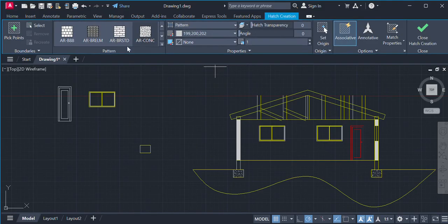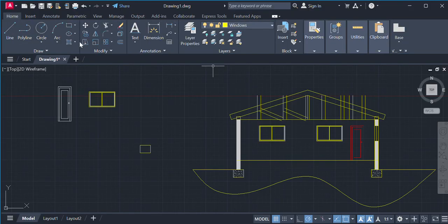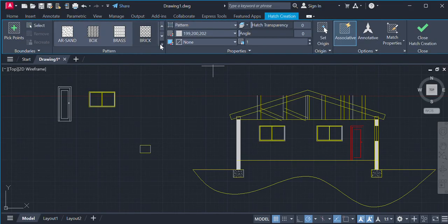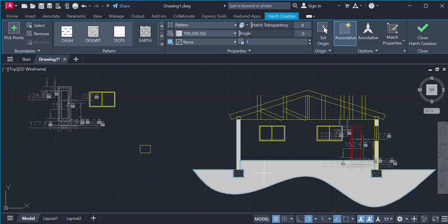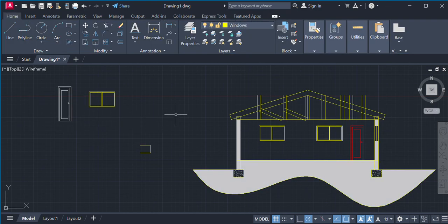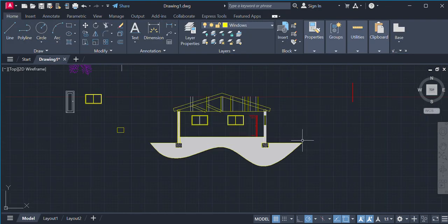Then we're looking for brick wall, for that small brick wall they've constructed between your actual wall and your foundation. Then we're gonna look for earthworks. Do they have it? Yes, they should. Then you can insert earthworks on there, and that will essentially be how you go about constructing your sectional plan.